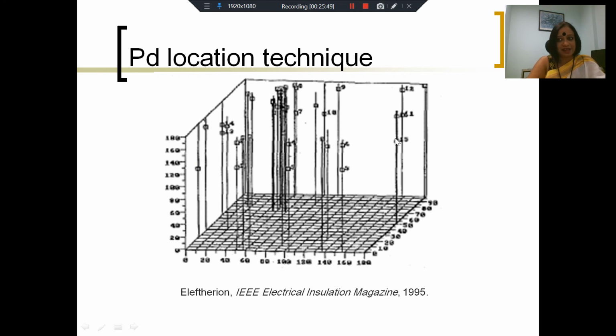In that way, you can figure out that there is a very strong likelihood that some of these might be stray signals, maybe inaccurate readings, but where you have a large number of signals clustered together, it is possible that it is in that location that you have a major source of PD. Remember, it is always possible to have more than one source, but if we can locate the major source, where the highest PD magnitude is taking place, that too can be advantageous.